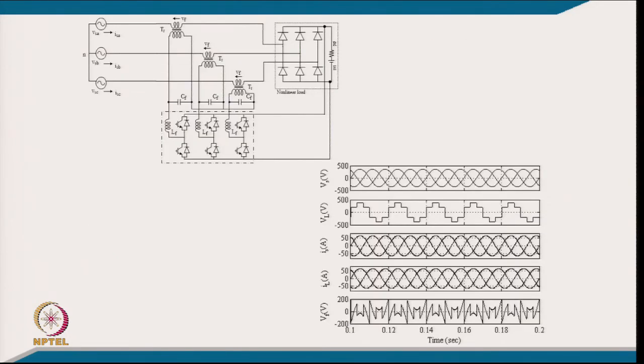Well, this is the system that we have, typically a voltage fed load. After the diode rectifier, we have a typically battery charging load, and this is the series active filter by which we are injecting the voltage in series with the line, and the DC link of series active filter is connected across the battery of the load. And the very purpose of series active filter here, of course, is by appropriately injecting a suitable voltage, to maintain this supply current sinusoidal, balanced and in phase with the supply voltage, so that the unity power factor operation is achieved.